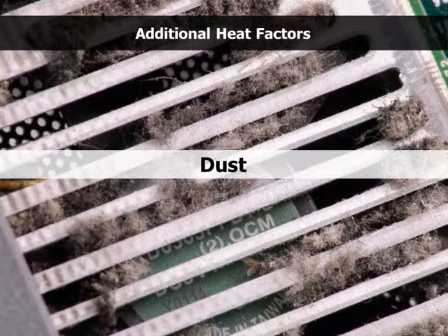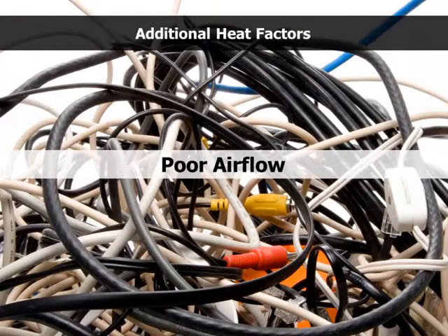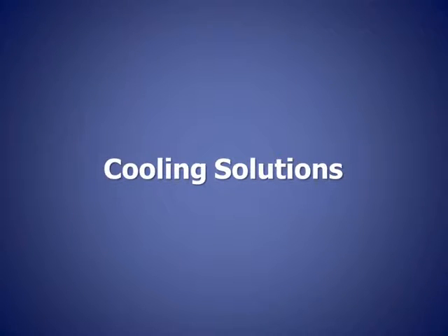place, thus creating heat. Poor airflow can be another factor, and this type of airflow issue is not related to dust and clogged vents per se, but for instance, it could be an excessive amount of cables in the wrong location. There could be open vents and open expansion slots and so forth. It can create poor airflow through the system. These systems are designed for the air to be evacuated out in order to be able to keep the system running efficiently.